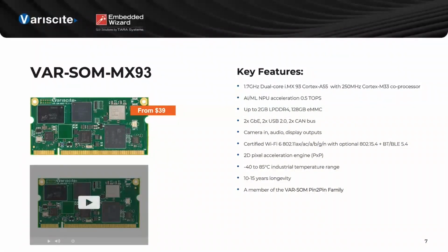That is a SOM based on the NXP dual-core i.MX93, which features a Cortex-A55 with a Cortex-M33. It integrates machine learning with an NPU of 0.5 TOPS. The memory is available up to 2 gigabytes, and the eMMC is available up to 128 gigabytes.